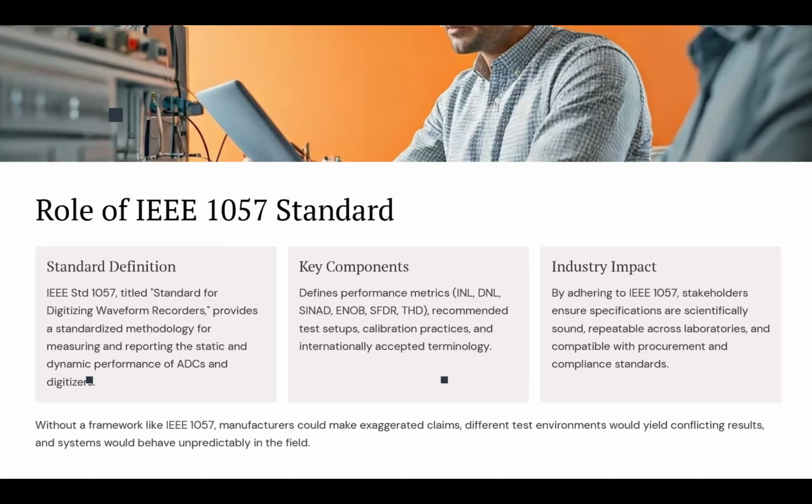In another part, it provides us guidance for calibrating the instrument and the procedure. So we make sure that, for example, we have zero drift, we have accuracy, and we know the errors that we introduce to the test. Because no matter what, we cannot have an instrument that has zero error. Calibration would enhance that situation, but it never mitigates it fully.